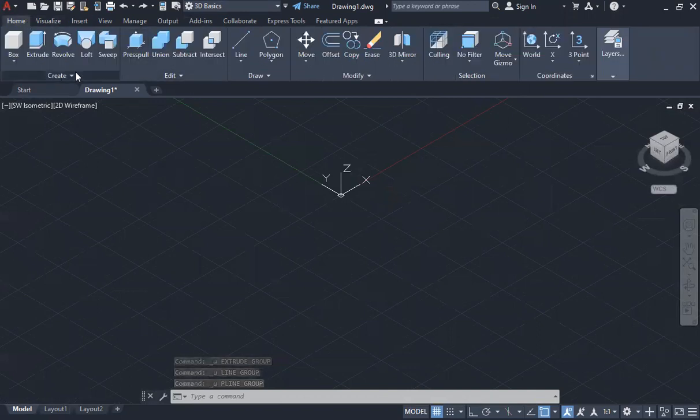Okay, covered in your lectures were the 4 basic three-dimensional modifying tools. You have the extrusion, which is basically you draw something on a flat surface and then you extrude it up to give it a thickness into that Z axis. You have a revolution where you draw a surface and then you revolve it around an axis. You have lofting where you have 2 different profiles set at a different distance, and you can create a nice smooth transition from this profile to this profile.